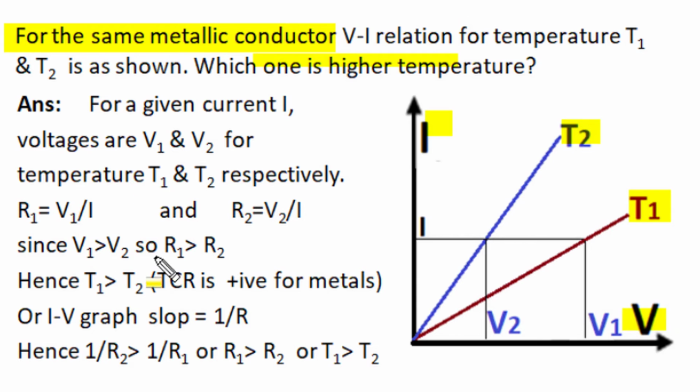Now resistance is the voltage to current ratio, and for comparison, if we make the denominator current the same, the corresponding numerator values for temperature T1 is V1 and for T2 it is V2. So for two different temperatures, the two values of resistance R1 and R2 are given by these expressions, and for the same current V1 is higher in magnitude as compared to V2.